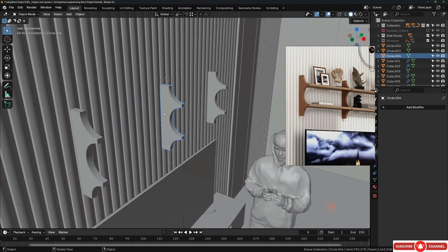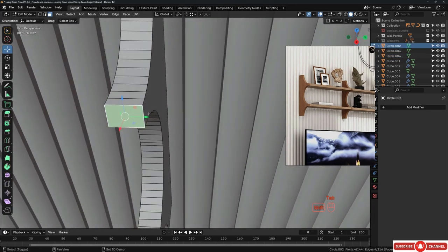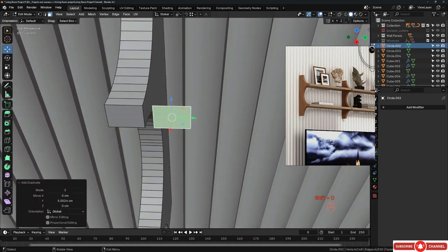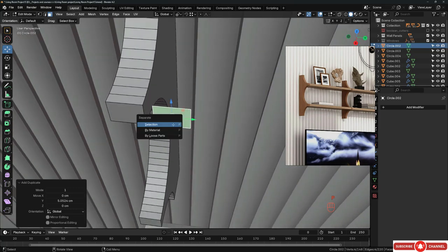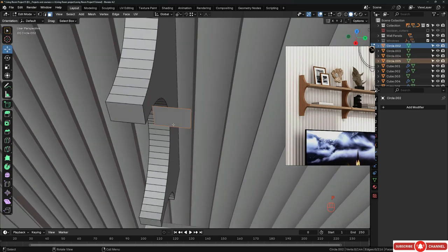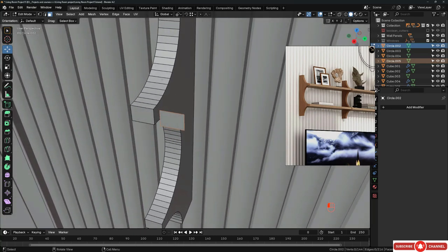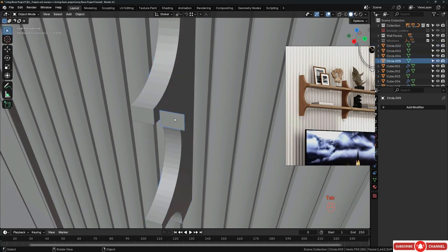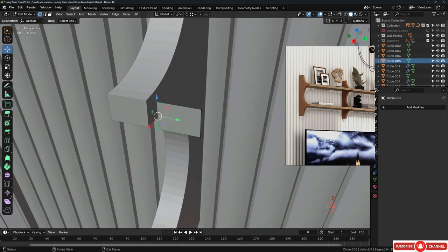All right, after that, we need to create these pieces. So I guess we can start from this one. I will tab and grab this face to use it. I will hit Shift D to put temporarily right here, Shift D and move it to the Y, and then hit P and then S to separate this, or let's say to detach this. All right, now we are in the edit mode of this object. I want to get out, tab, and then select this one and tab in. And now let's start working on this one.